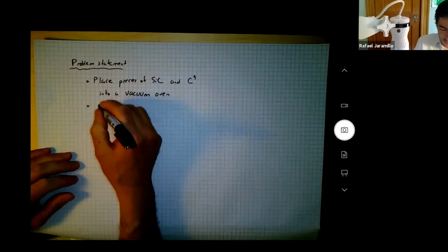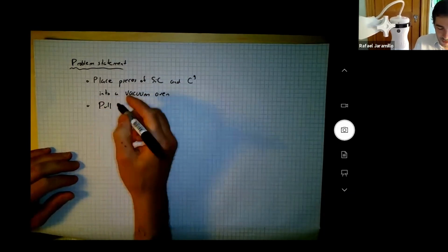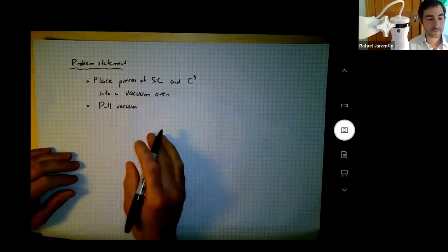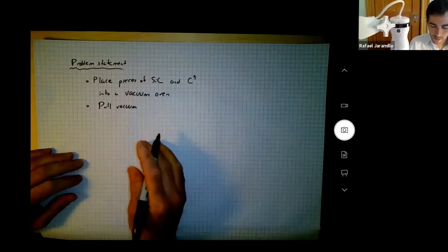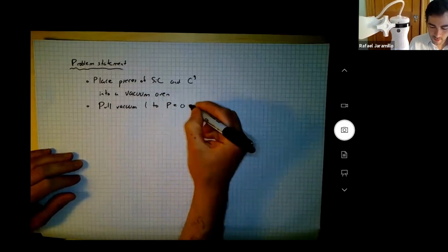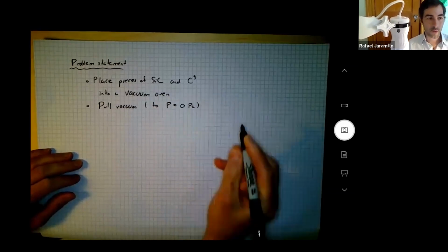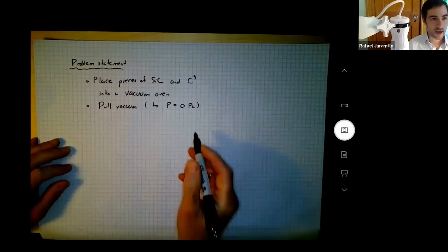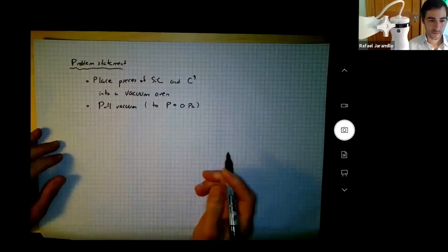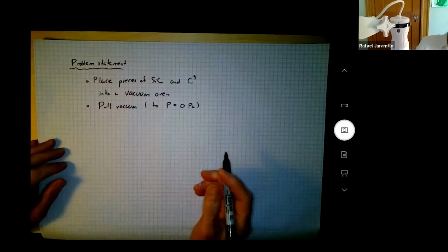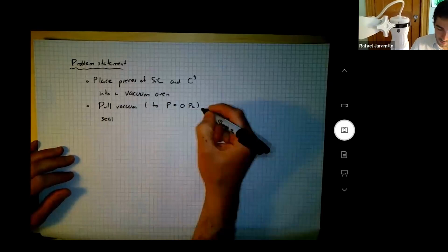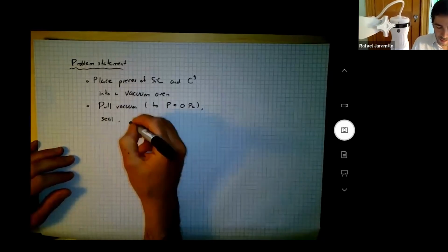And now I'm going to put them in the oven, and I'm going to pull vacuum. That means evacuate the oven. And we're going to pull this vacuum to approximately 0 pascals. So, there's no absolute vacuum, but on this scale, your gauge is reading 0. Okay. We're going to seal it. Pull vacuum, seal, and then heat.